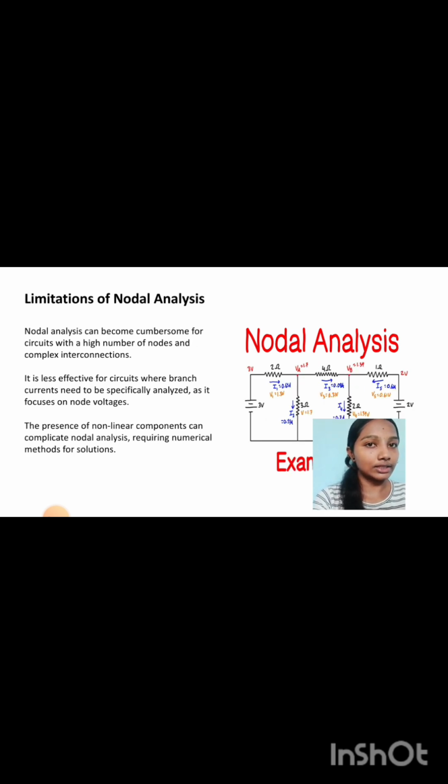Limitations of nodal analysis. Nodal analysis can become cumbersome for circuits with a high number of nodes and complex interconnections. It is less effective for circuits where branch currents need to be specifically analyzed, as it is focused on node voltages. The presence of nonlinear components can complicate nodal analysis, requiring numerical methods for solutions.